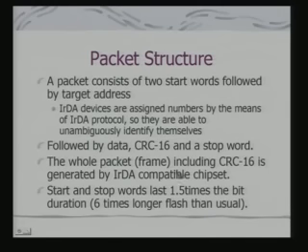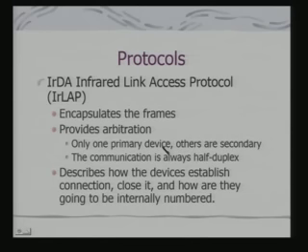The whole packet or the frame including CRC16 is generated by the IRDA compatible chipset. What is the CRC16? This is for doing error detection as well as subsequent error correction. There are a set of protocols which have been defined for this purpose, just like you have on IEEE 1394 a layers of protocols. Here also you have a layers of protocols.